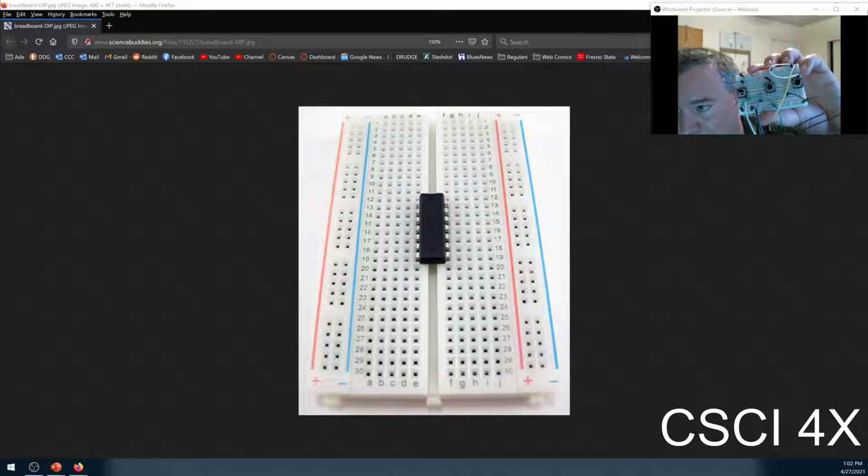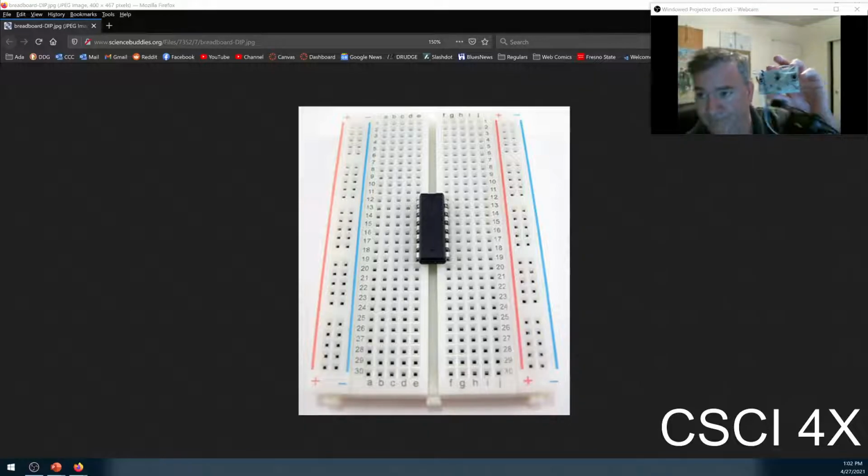The output pin of the switch goes to a resistor, and that attaches via wires to the LED. The output of those LEDs goes into the bottom rail here where my thumb is. All 3 of those LEDs are hooked up to the ground rail, which goes back into the Raspberry Pi, completing the circuit. And thus, when you push the button, the light turns on.